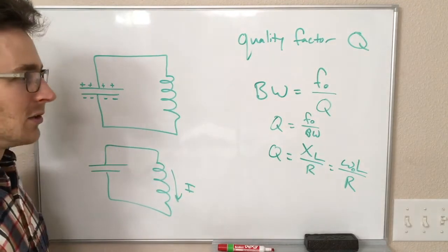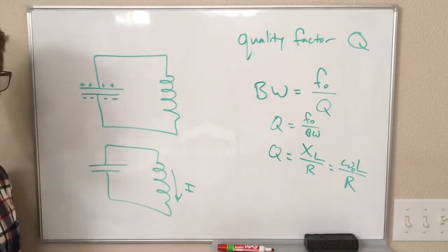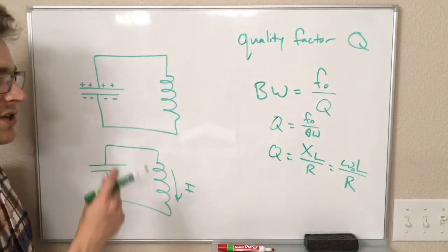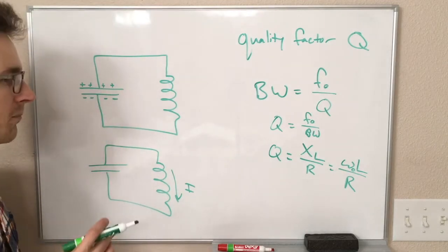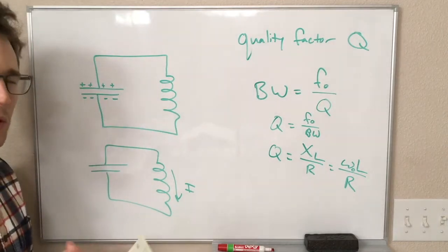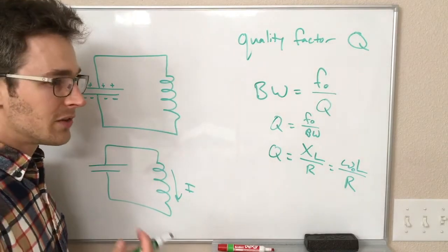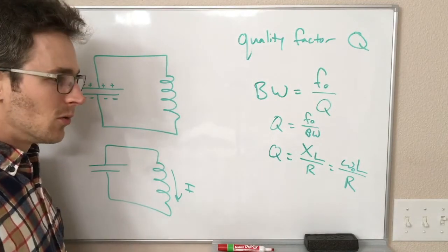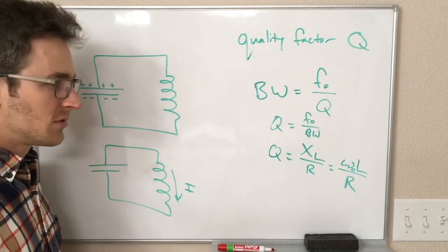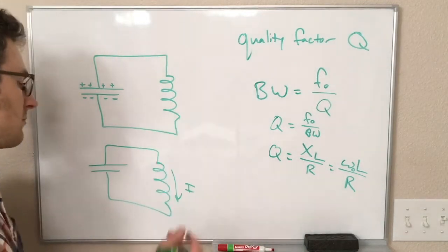So the way I think about it, you kind of have this charge sloshing back and forth between the two plates of the capacitor. In our mass and spring analogy, the capacitor is kind of like the spring storing this energy by stretching the charge apart or something like that. And the inductor is the mass. The inductor is giving some inertial mass to our current. So once it starts going, it's hard to get it to stop going. It keeps going in the other direction past equilibrium. So that's what's going on here.